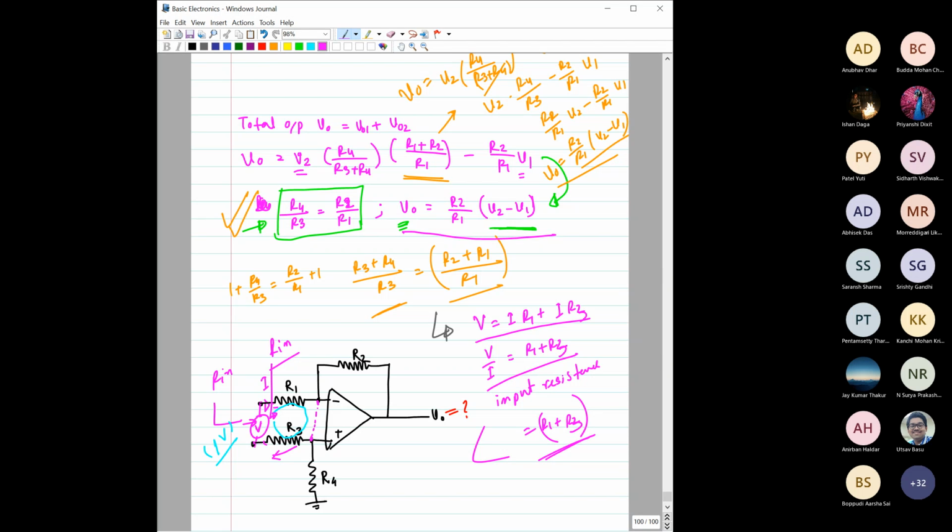Sir, the V that we are using here is applied across those two terminals of R1 and R3. Yes, it has been applied to this. This is a known voltage, right? So suppose you have a battery, you can attach that battery between any two terminals. We have connected it between these two terminals. And suppose that battery also has the provision that it shows what is the current that has been supplied by the battery. So you know the voltage, you know the current. I'm saying for some practical case. Then it is quite easy to say that the internal resistance that has been seen by this battery is this one. Is this part clear to you now?